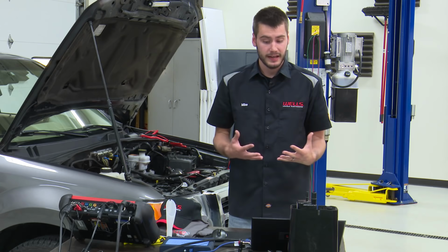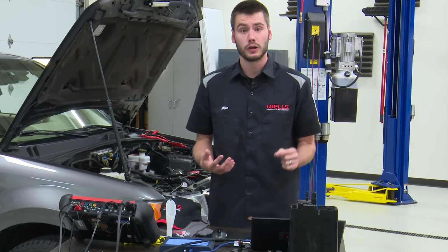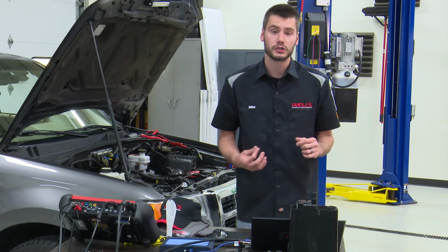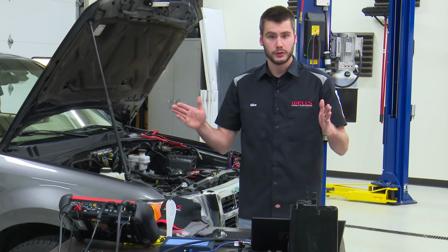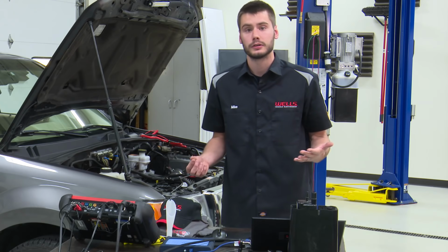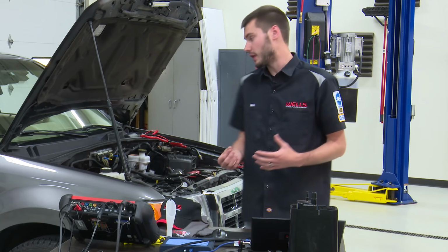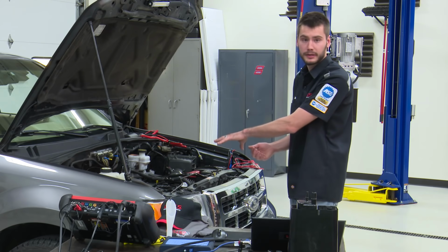You need to monitor that, and then you need to be able to jump the vent closed and the purge solenoid open for a short amount of time, seal up that front door and back door, and watch your fuel tank pressure, right? Watch what happens. You have a vacuum pump in the engine.